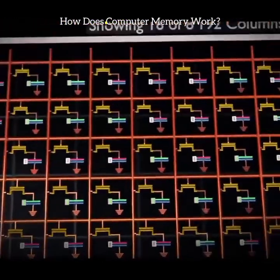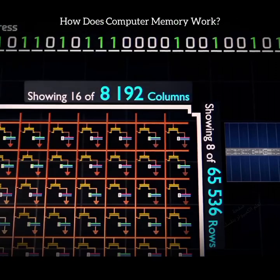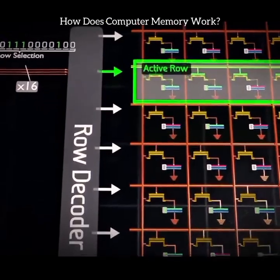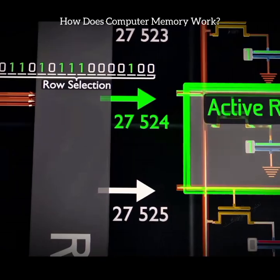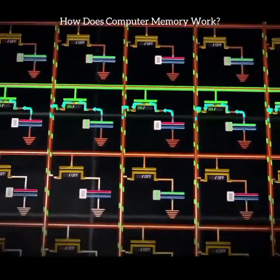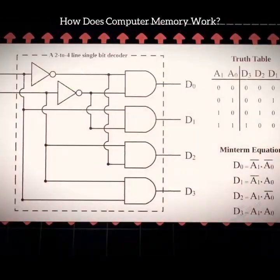As mentioned earlier, within a single bank there are 65,536 rows and 8,192 columns, and the 31-bit address is used to activate a group of just 8 memory cells. The first 5 bits select the bank, and the next 16 bits are sent to a row decoder to activate a single row. For example, this binary number turns on the word line row 27,524, thus turning on all transistors in that row and connecting the 8,192 capacitors to their bit lines, while at the same time the other 65,000-ish word lines are all off. Here's the logic diagram for a simple decoder.